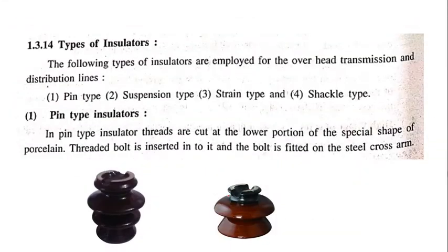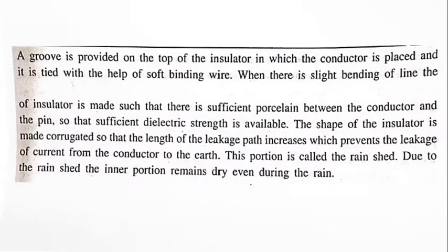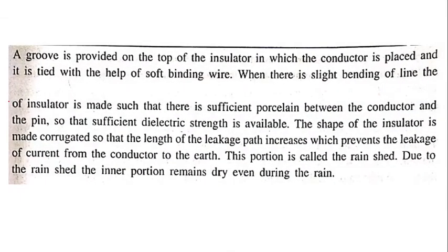Over here, as you can see, is the groove where we can easily place our conductor, or if there is a little bit of bending at the time, we can bind it with binding wire. When there is a slight bending of the line, the insulators are made such that there is sufficient porcelain between the conductor and the pin. So sufficient dielectric strength is available.